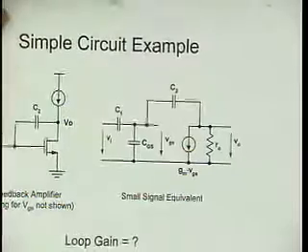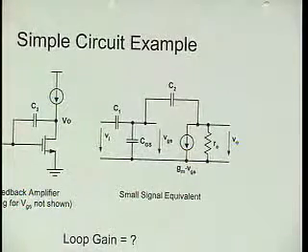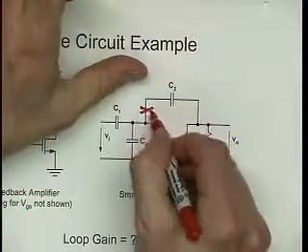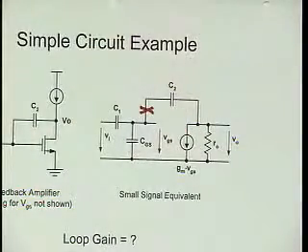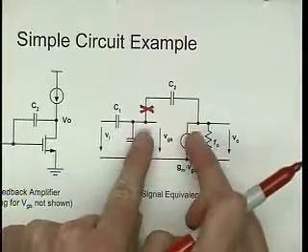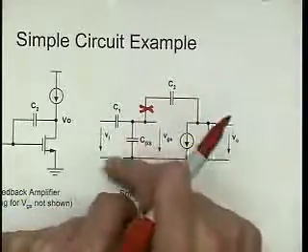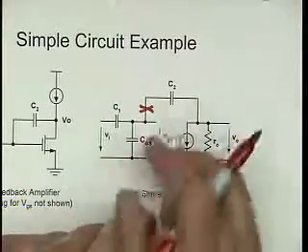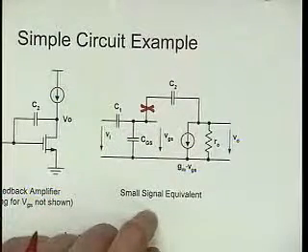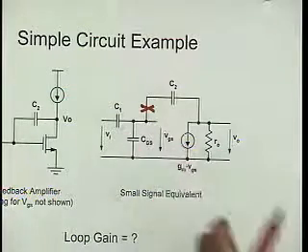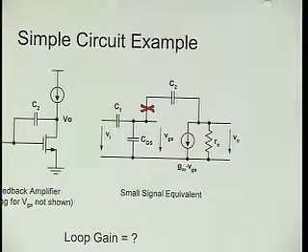But breaking the loop isn't all that easy. If, for example, I break my loop here, the trouble is that before I had broken the loop, my amplifier also was loaded by C2 and all of the stuff hanging here. By opening the loop here, I suddenly changed the load on our amplifier, and that probably changes its frequency response. Consequently, I'm now measuring a circuit that I didn't really build.